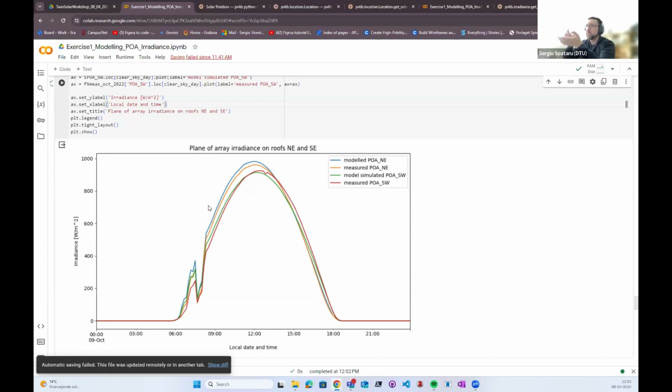But we can trust our models, especially since we use pvlib functions. The easiest place to make a mistake is in the solar position model, but there we use the pvlib functions. So sometimes you can use the model to verify if your sensor is correct, though most often you use the sensor to verify if the model is correct.